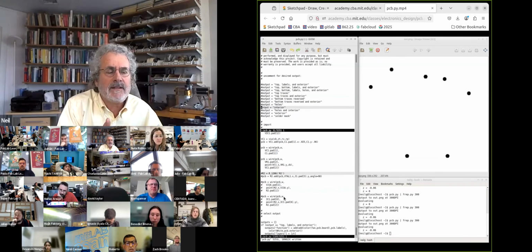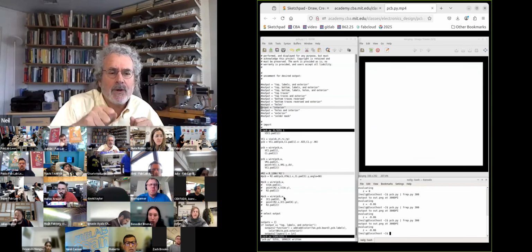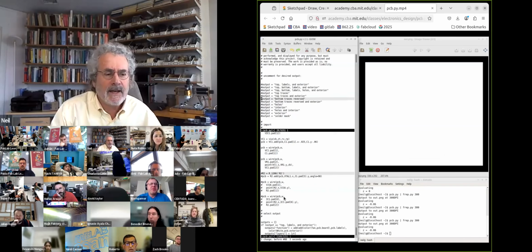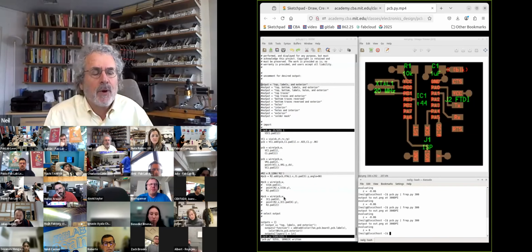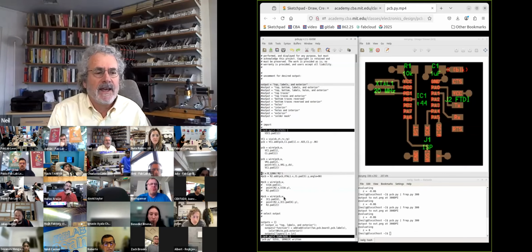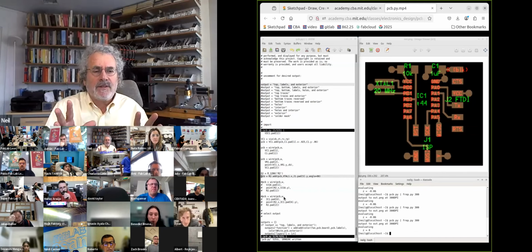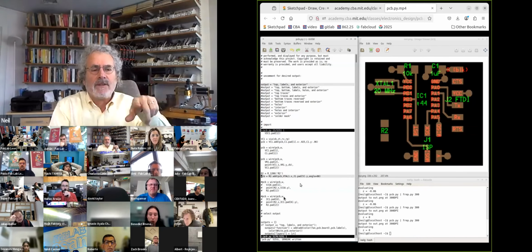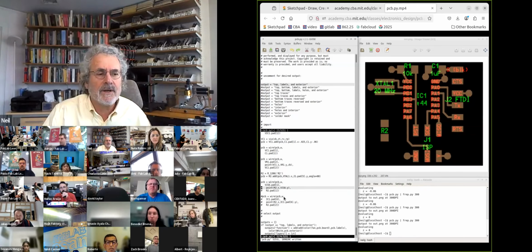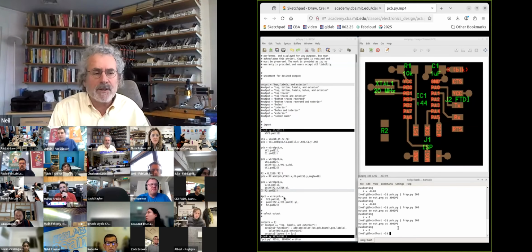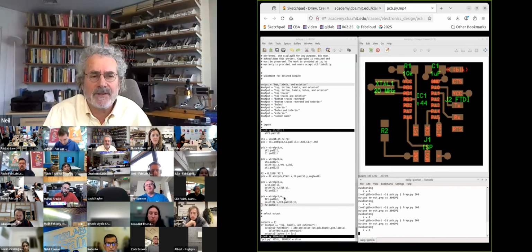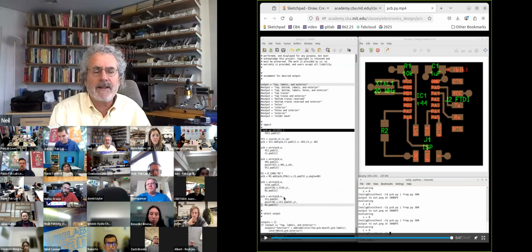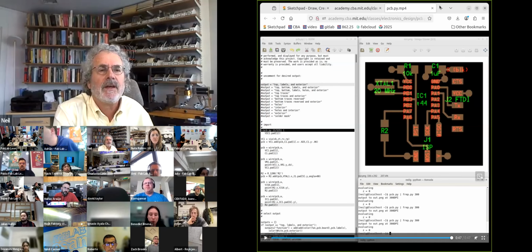And then instead of using my mouse to click and drag, what I do is I describe relationships. So I programmatically say, I want to place a resistor and align it with the crystal and the connector, and then I want wires to go between them. And so I'm describing relationships in a way you can't do just by clicking and dragging.